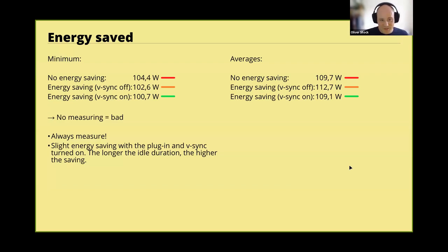So this, of course, underscored for me the importance of measuring, because you can see in the Unity editor how many frames are being rendered, but that does not necessarily translate to what's actually happening in your computer. So you can be smart and have a good working mental model, but in any case, the best thing is just to measure it. Use the profiler, use hardware that actually tells you what's really happening and not what you think might be happening.